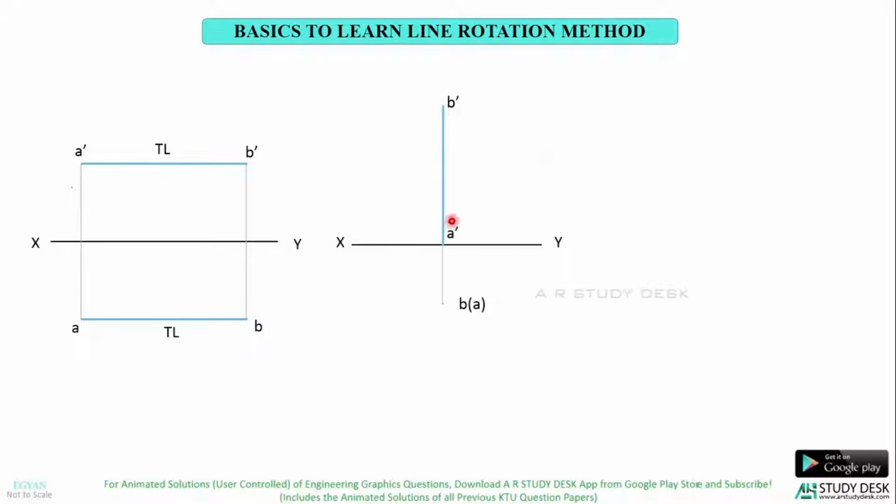Now, is this front view the true length? To know that, just look at the top view. In the top view, the line is parallel to XY line. So, in the front view, you get the true length of the line.